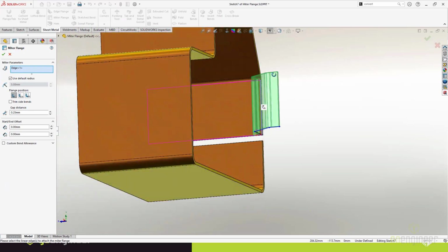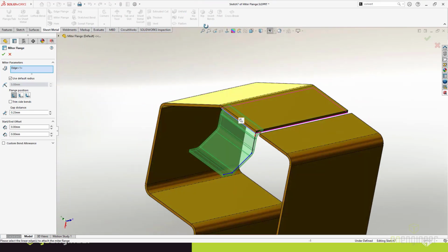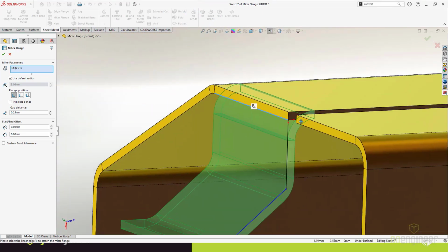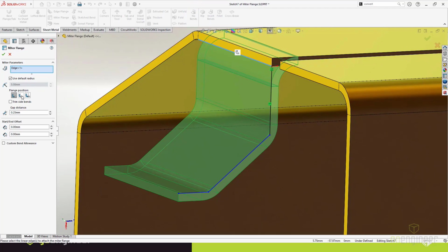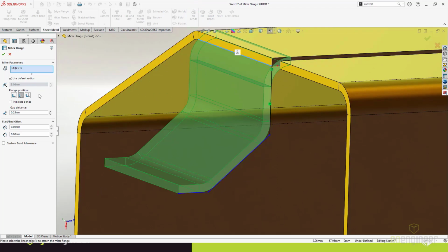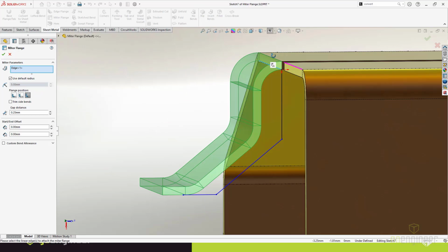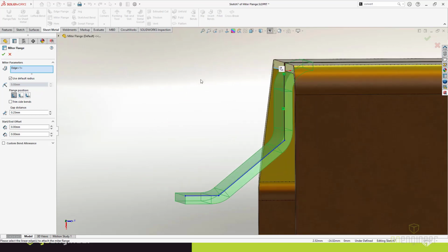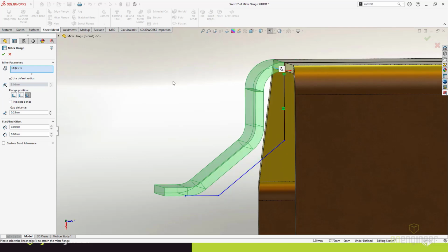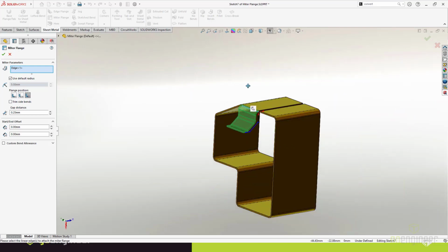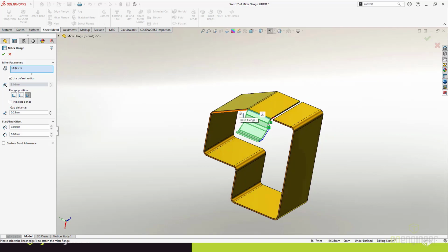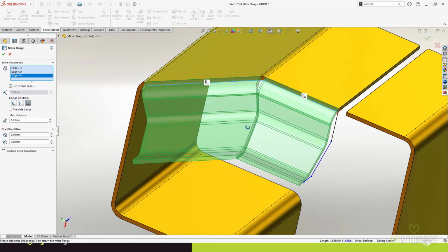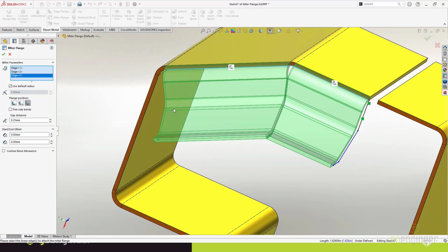What it'll do initially is put that part in place, and like all other sheet metal features, it's going to give you options to change where that radii blends off the existing geometry. So if you just want the radius to roll off the edge, or if you want this outside face to be tangent with the existing outside face, those are the choices there. But what makes this one super powerful is at any point I can incorporate other edges, and where those overlap each other, they're going to give you the proper gapping there.